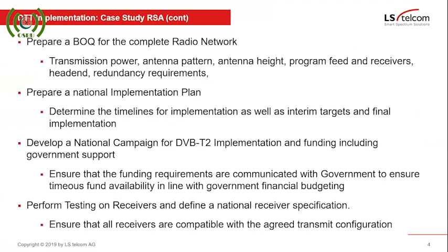Obviously, during this whole design process, there's also the whole design of the network. And we had this one slide earlier today where we looked at antenna gain, transmitter power, feeder loss, cable loss, connector loss, and all of that. And we eventually came out with a transmitted power specification in accordance with the ERP that appear in the broadcast plan for the country.